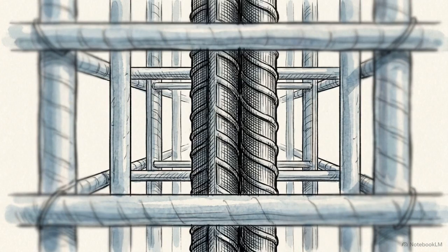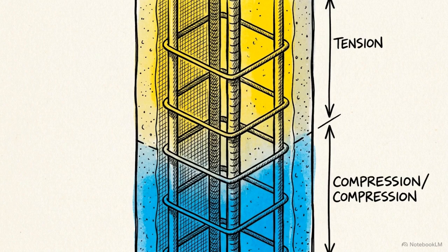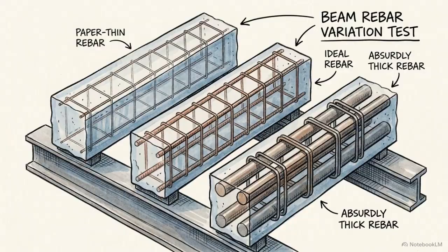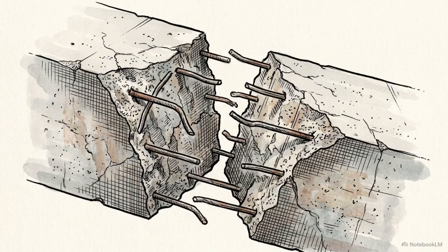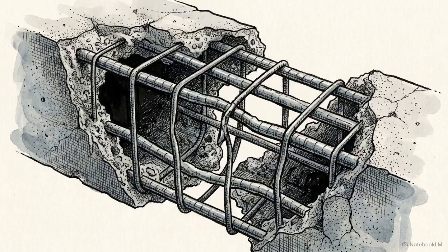We finally reach the absolute center of the structural node: the thick, longitudinal main bars carrying the primary tension and compression loads. Core steel must operate in a strict Goldilocks zone. Minimum limits act as an insurance policy against sudden, brittle fracture when the concrete inevitably cracks, while maximum limits prevent dangerous voids during the concrete pour.